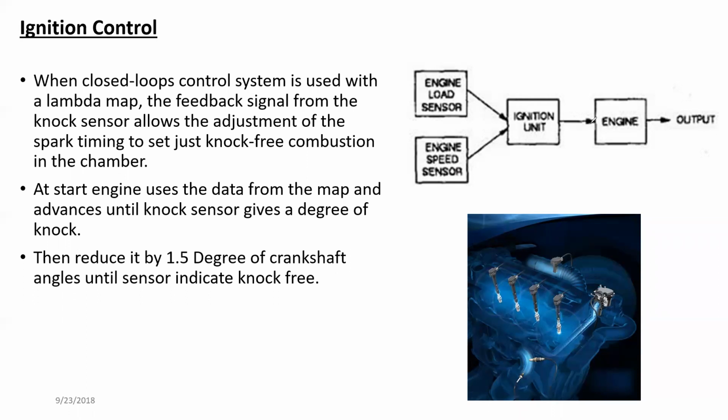If there is any possibility of knocking, the ignition system automatically retards the ignition timing by 1.5 degrees at a time, until the knocking stops.